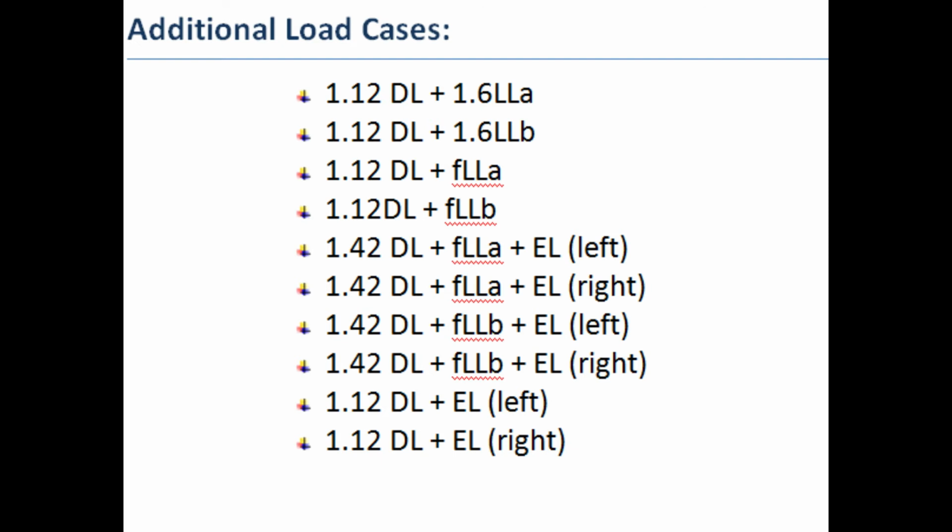Before we proceed to the drafting part or the drawing of the design frame, we need to add load combinations or add basic load cases. In this case, we are adding 10 load cases, which are the following.